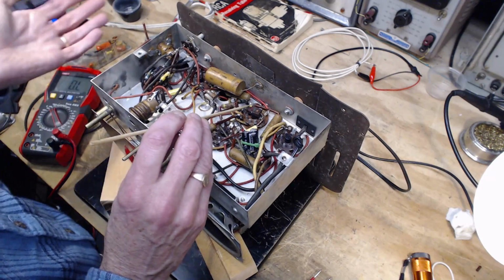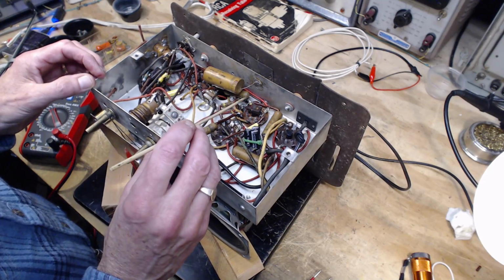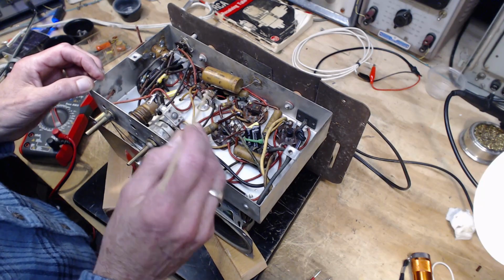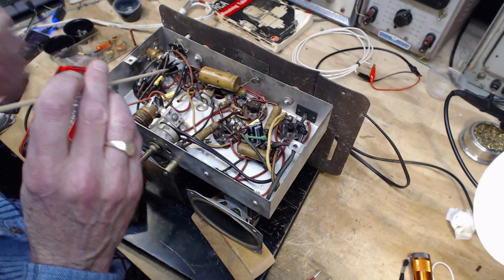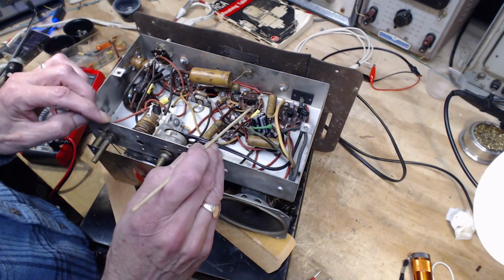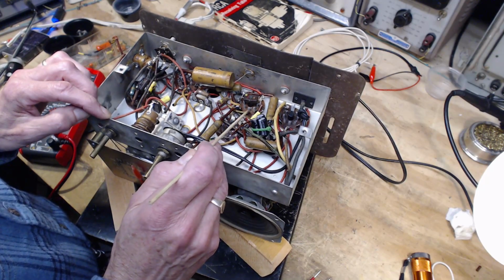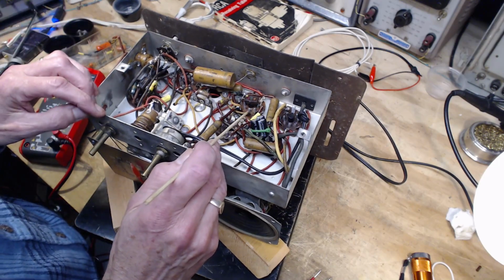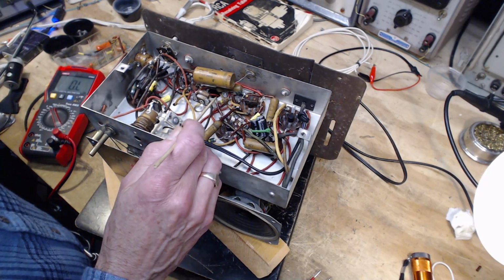8 is the cathode, and the cathode is on B minus. So here we've got a capacitor connected to B minus. This resistor is connected to a black wire which is going down to the IF transformer. So there's another wire coming up here, and it's connecting to these two terminals which are bridged. There's a wire between them. These are the two diodes, and they've just been shorted together to work as one bigger diode. So this is the rectification of the output of that IF transformer.